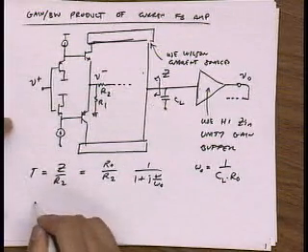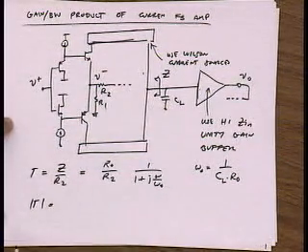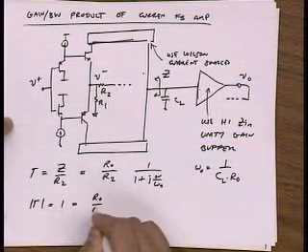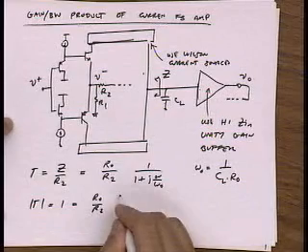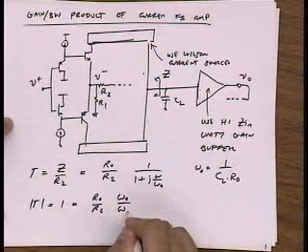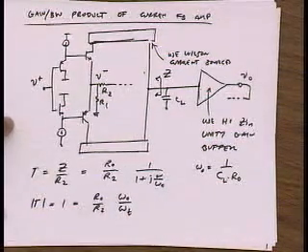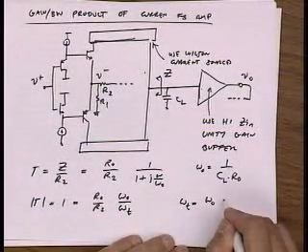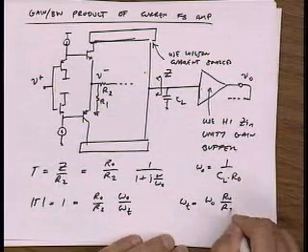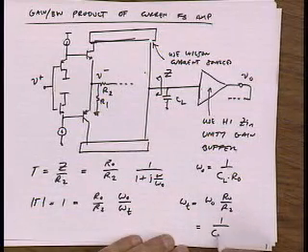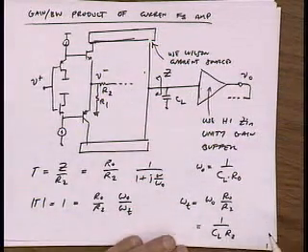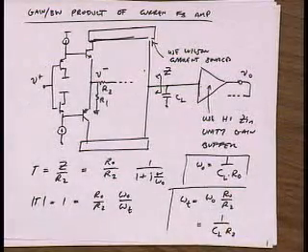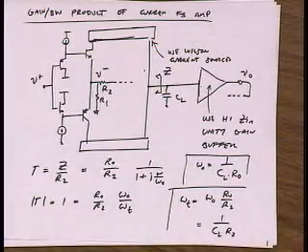All right, also, if we're interested in the unity gain frequency, we set the loop gain equal to 1 and solve. So we have R0 over R2, approximately omega 0 over omega t. And so we have that omega t is omega 0 R0 over R2, or it's equal to 1 over CL times R2.